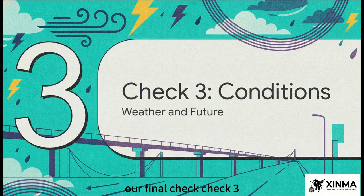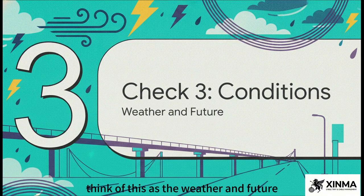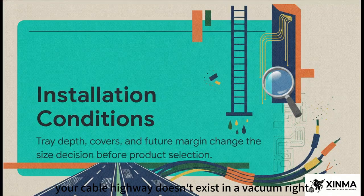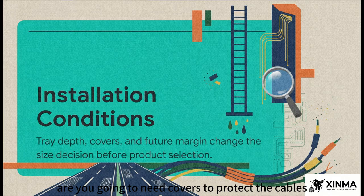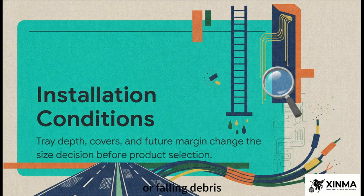Our final check, check 3, environment conditions. Think of this as the weather and future. Your cable highway doesn't exist in a vacuum, right? It exists out in the real world. Installation conditions are factors that must be decided before any specific product is even selected. For instance, are you going to need covers to protect the cables from harsh weather or falling debris? What about the tray depth? And crucially, this is a big one.